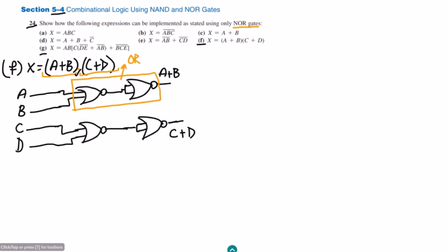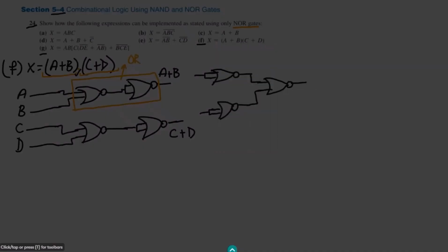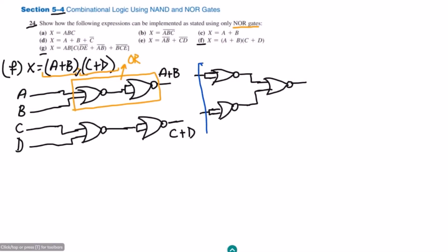Because here the two have to be multiplied. The AND gate here, as we have previously seen, by using the NOR gate, the AND gate implementation will be like this: this is the first NOR gate, this is the second NOR gate, the two inputs are combined together, here the two inputs are also combined together, and these are given to the final 2 input NOR gate. So let me give it to this one here. Here we have this NOR gate, and we can very easily see that this is the implementation of the AND gate.